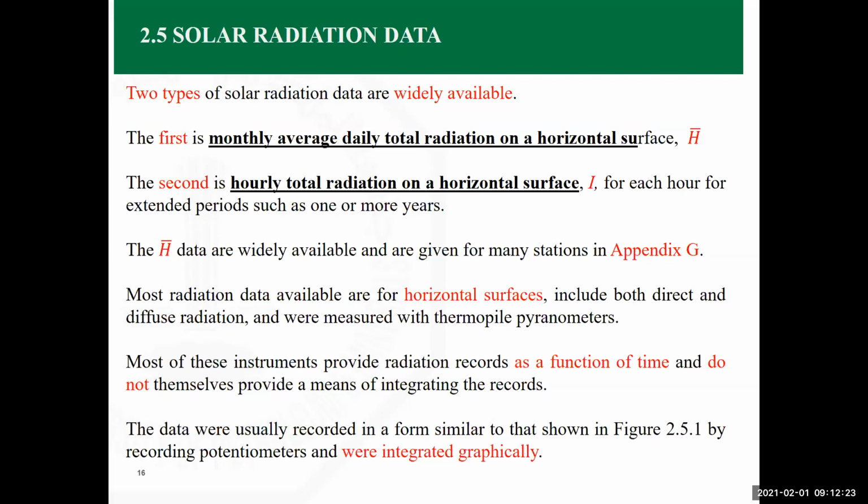Sometimes, when students are working on a solar energy application that we have, I ask them to take the measurements only once after every 15 minutes or maybe half an hour, because the change in the radiation flux is not significant over a small period of time, unless there is a cloud passing and it affects the readings, then definitely we'll need to account for this.